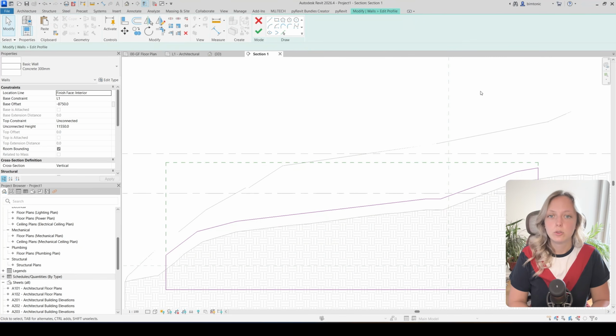But we also need to draft the bottom of this wall as well. A lot of people make mistakes by simply cutting this wall in many other pieces and then adding them the footing. Basically, that is the slower way. The faster way is actually creating all of this as one wall. That way you can automatically add the footing to each of the planes that you have in the bottom of this wall. So that's what we are going to do today.